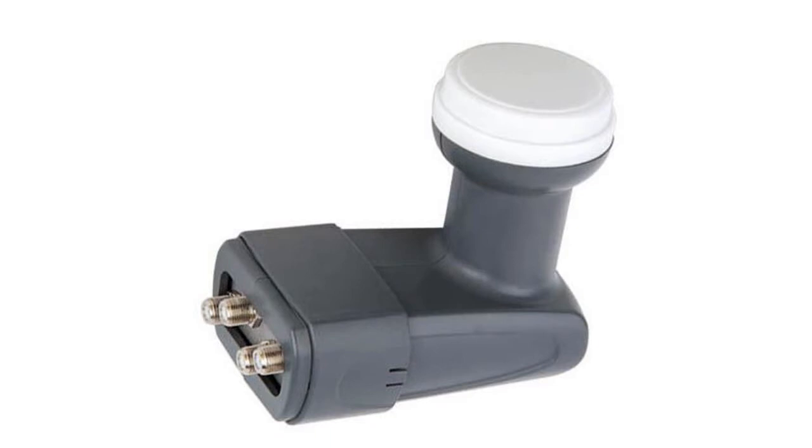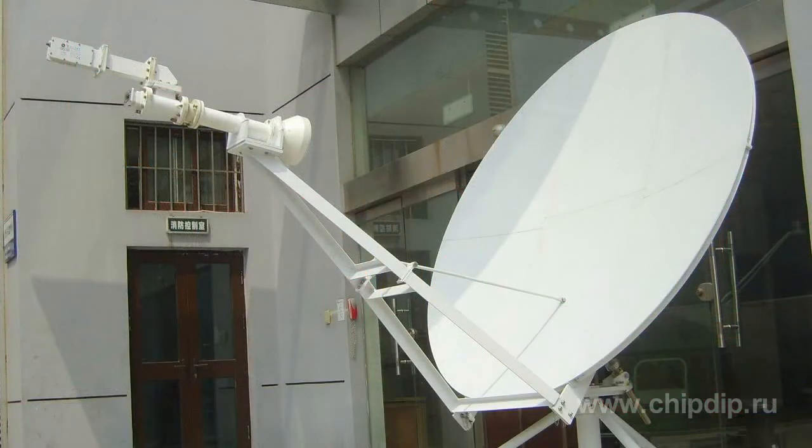I think so, as the performance of receiving antennas, called dishes, is proportional to the number of wavelengths across its diameter, and as a wavelength decreases with the increase in frequency, the higher the signal frequency is, the smaller the dish required. It doesn't affect the reception, and it is easier to install and operate. C-band requires antennas from 2.5 to 4.5 meters in diameter, while Ku band can be used with antennas from 0.5 meter to 1.5 meters in diameter.